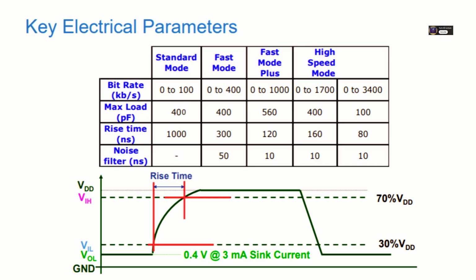This leads directly to timing violations. The devices expect the signal to be high by a certain point in the clock cycle, and it just isn't. You'll see data errors, unexpected NACKs, maybe communication just fails completely. On a scope, the rising edge looks like a slow ramp instead of a sharp step.